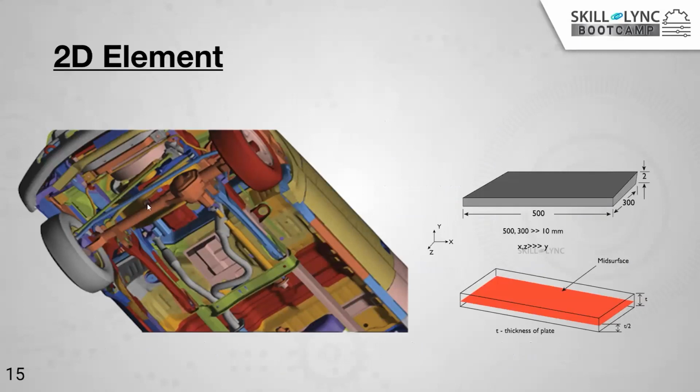This is an example of 2D shell meshing. This car model is created using 2D shell meshing. Had you used 3D meshing, it might have increased the element count by a huge amount. The number of nodes might have gone to a very high amount, even above 1 crore nodes, which would have taken more than a week or 2 weeks or even months to solve a single analysis. By using shell meshing, you might have restricted the number of nodes to a lakh or 5 lakhs.